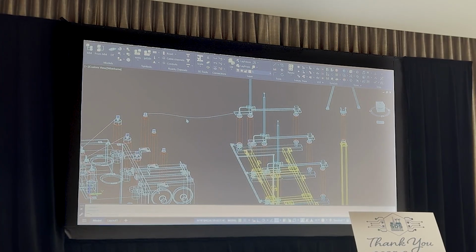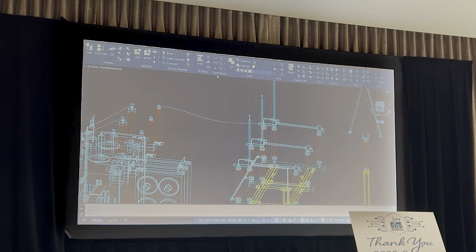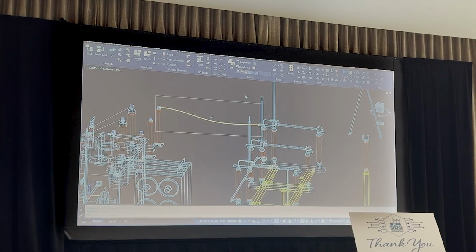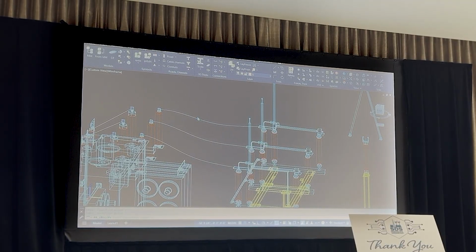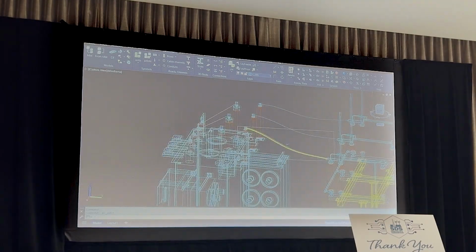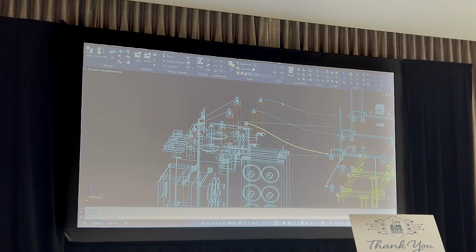So now, if I want to go use that same information to do a connection somewhere else, I can use this button over here that's copy. I can copy the properties of that connector or of that connection. And then I could just click points. And if we go back and check what you do by doing this PR edit after you selected it, we can see that that cable has the same properties, right? So that one will be very similar to this one, except it doesn't need the T because the T's already on that side of that connection.